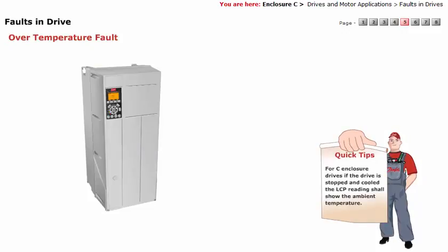For enclosure drives, if the drive is stopped and cooled, the LCP reading shall show the ambient temperature. If not, the temperature sensor must be checked. This can be done with the use of an ohm meter. The resistance at 25 degrees Celsius shall be 10 kilo ohms.